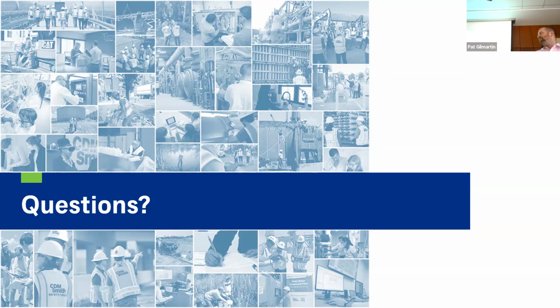And a lot of times, like I mentioned, 30 to 40% of the time, the contractors will come in and say, I'd rather do a different alignment based upon the equipment that I'm bringing. And so that's where, especially in urban environments, you want to make sure those variances for the utilities are noted, and you're showing those minimum clearances there, so you don't have issues.